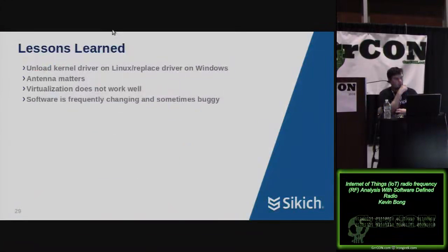So some of the key lessons learned, I've got a few more things to come on this after this. Some of the key lessons learned are the hitch to unload the kernel driver on Linux and Windows. And the other thing, you might have seen it there, is you can only really have one tool associated with your radio at a time. So even though GQRX wasn't receiving data, it had still grabbed hold of that USB device, and so GRC couldn't use it. I had to close the one tool to get the other tool to use it. Or if I'm using command line tools, I've got to close the other tools as well.